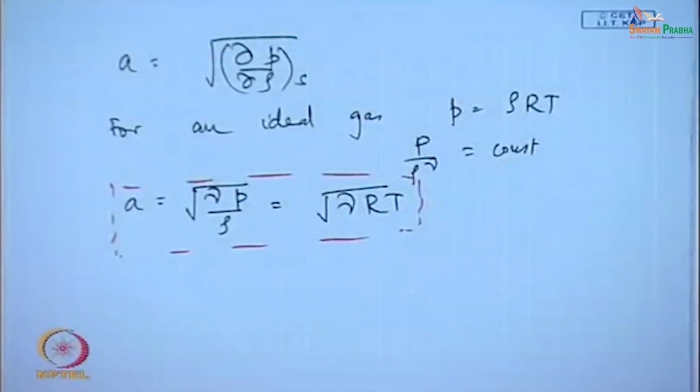We found that Mach number is important. Now, in order to calculate Mach number, what do we need? We need the velocity of sound. If we can relate the velocity of sound under those conditions with measurable parameters, it is going to be very convenient. So, the next thing we did is we expressed A in terms of the absolute temperature, or in terms of pressure and so on. We obtained that A is equal to root gamma R T. These expressions probably all of you knew from the beginning. What you did not know was probably how we arrived at them: why Mach number is important for compressible flows, and why A equals root del P del rho at constant S. Probably these things you were not very clear about earlier.